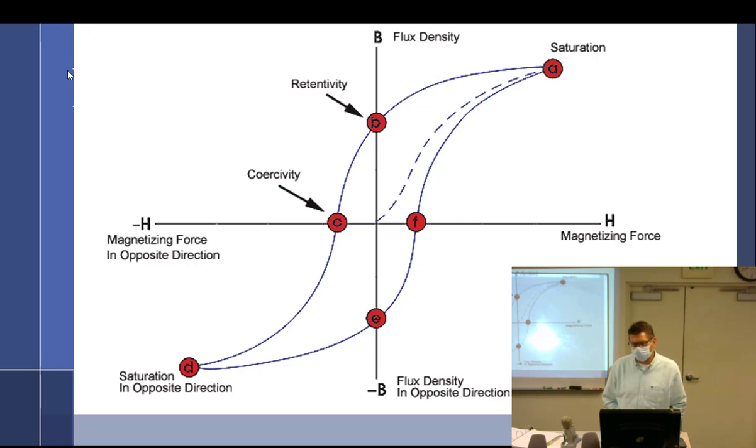Understanding a hysteresis loop helps you understand not only the magnetizing process and how much amperage you should be going into something, but also how it demagnetizes something. If I told you to demagnetize something that you magnetized, the idea is you want to scramble those little domains in there, right? So if you put it inside an alternating current coil, with the alternating current going back and forth, and you move it around in there, in theory it should just scramble them and be done. You can get rid of it, right?